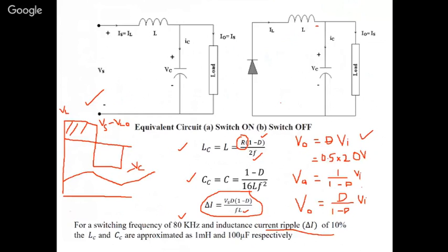But there is one more case where the inductor current becomes zero. It depends on the inductor value. Say it is increasing and here it has become zero, and after that it again increases when you switch on. So this is said to be discontinuous conduction mode.